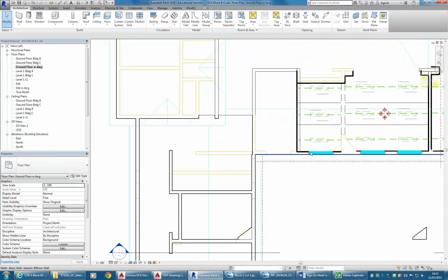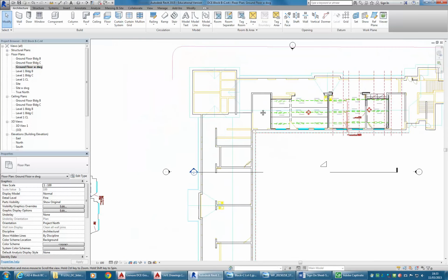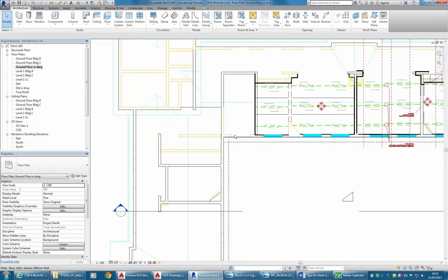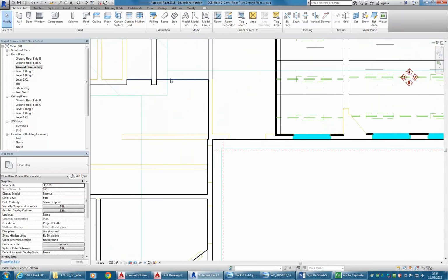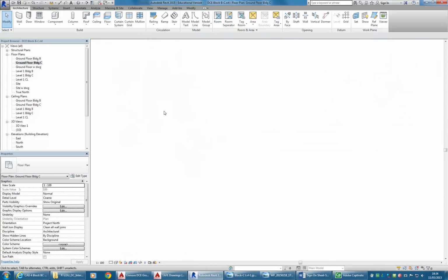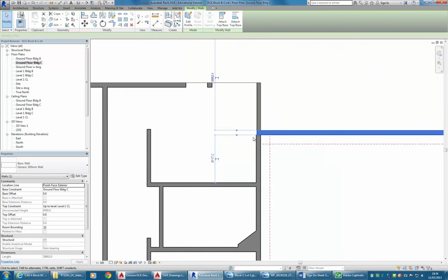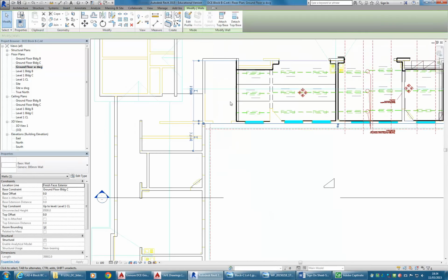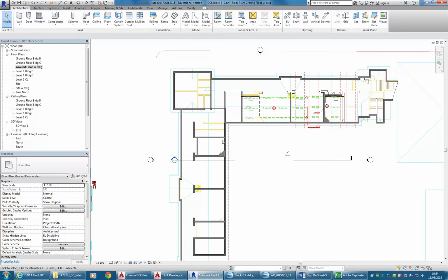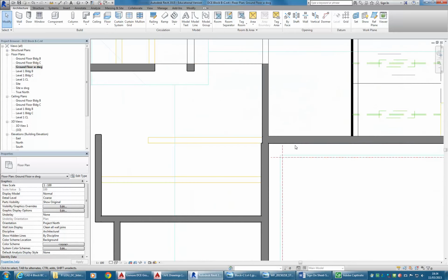And so then just remember, if you have issues seeing what you think should be there, just check that you're working on the level that you think you are. It's going to be a little bit complicated when you have those two different floor levels. So there is definitely a wall coming across there, it's just not showing properly in this view. So I'll just check a couple of the settings there. It's in wireframe, but I'm going to also make sure that it's in coarse view, and that way it's easier to see the walls. I don't really need to be able to see through those walls, so coarse is a good option there.